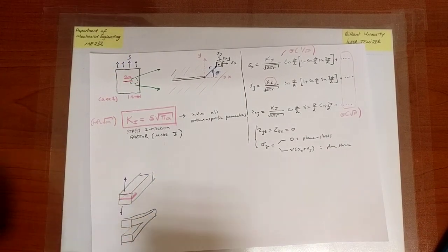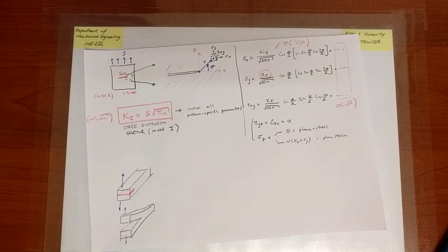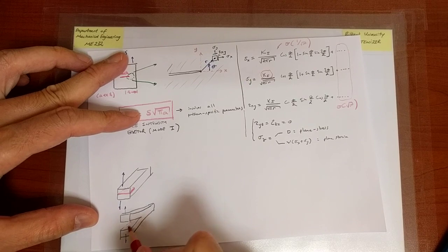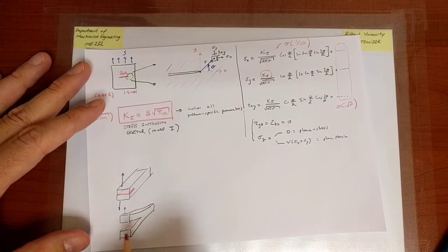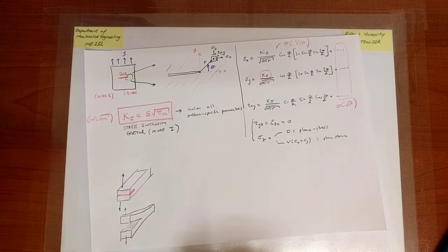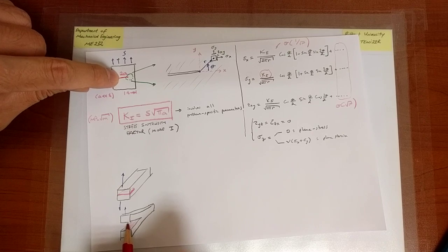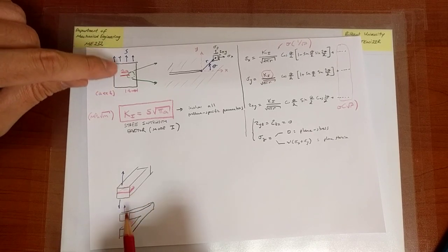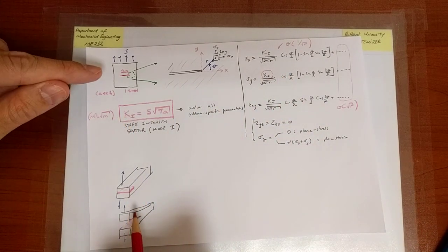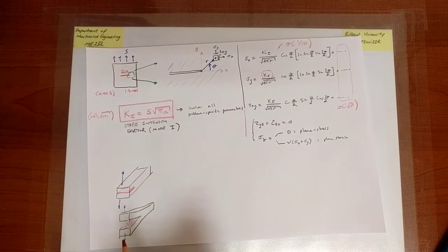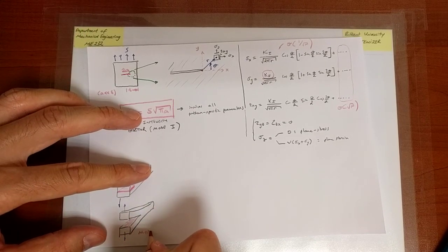Okay, so I am pulling, right? And because I pull, the surface of the crack will part from each other, and I open the crack. So this is mode 1. I try to open the crack. The geometry is not the same for the two problems, okay? So these fields are not directly applicable, but the idea is similar. It's a mode where I try to open the crack. So this is mode 1.